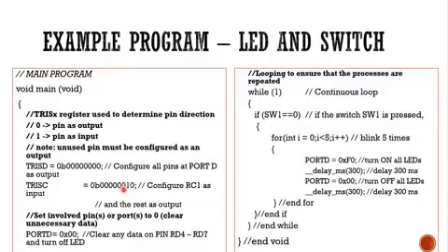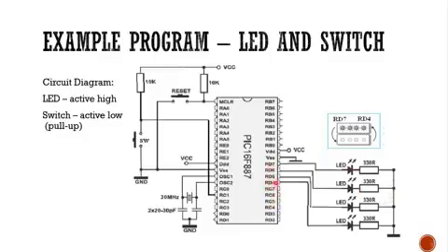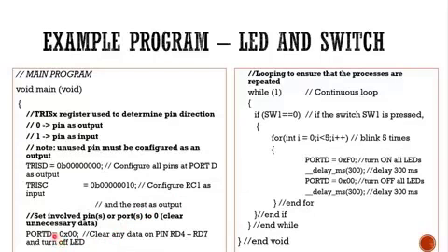And then the rest. You see, even though the value here is 0, this means that C0, C2, up to C7 will become output, except for C1, because we are setting the whole port, the whole bit from port C. After you have properly configured the direction of the data for port D and also port C, you can write the output value for port D. So you write 0, because you want to clear out any initial value from port D.